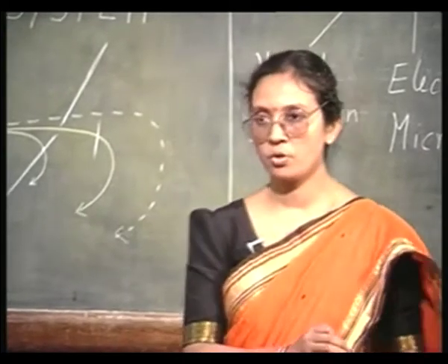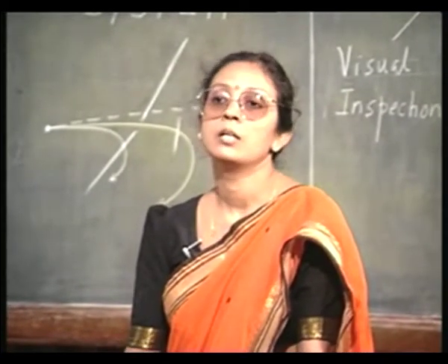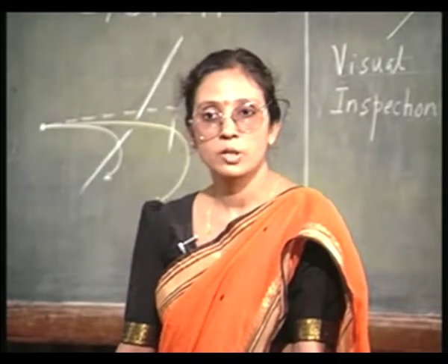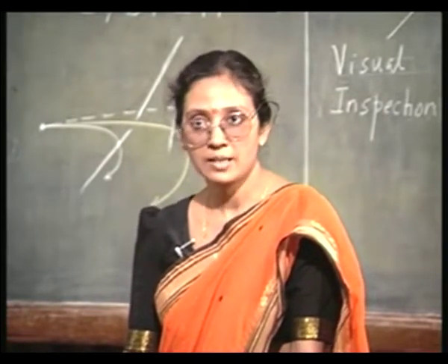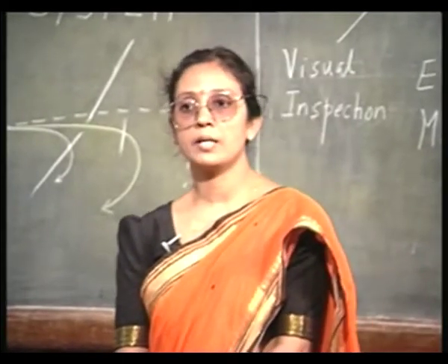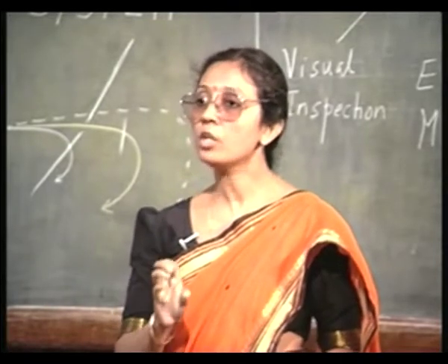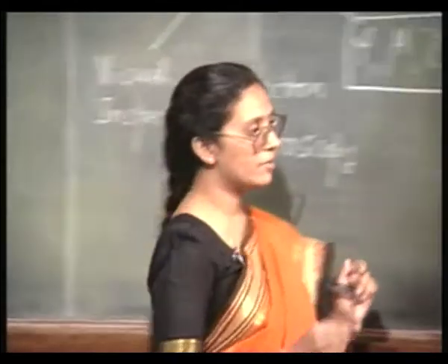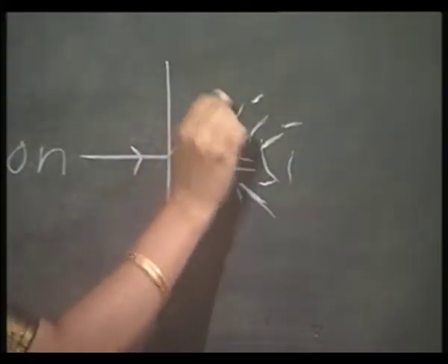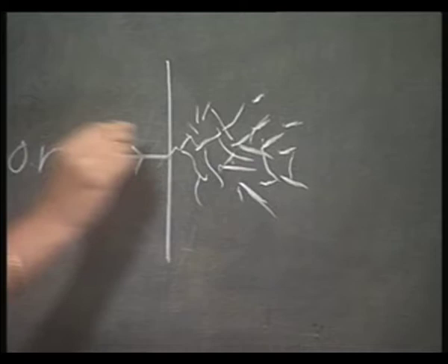So, because it transfers a larger amount of energy to the lattice atoms, those lattice atoms in their turn will again cause dislocations, and I will have multiple dislocations. At the same time, since the incident ion is getting deflected only by a small scattering angle, I will have the maximum damage within a small region. Agreed? So, what I will have is actually a horribly damaged region, but within a small volume.